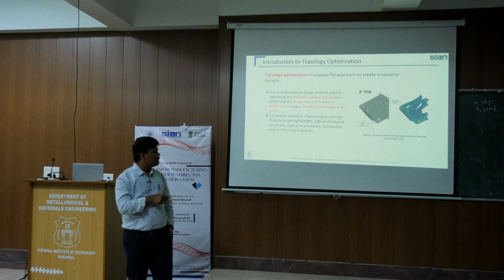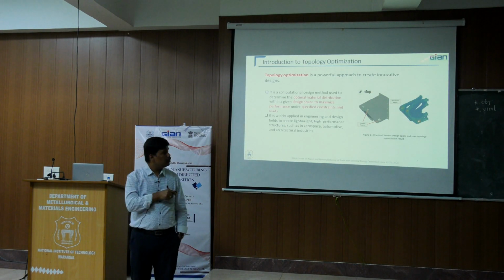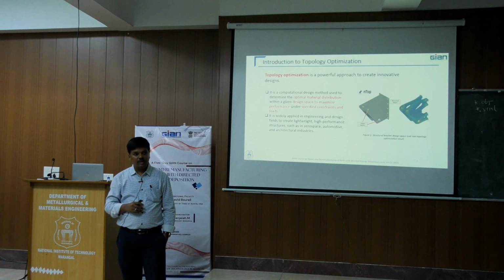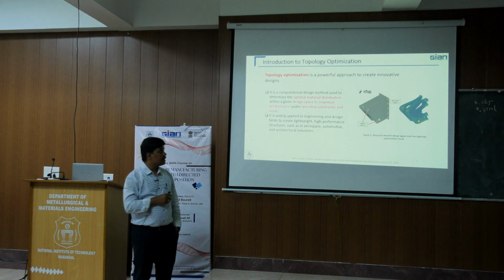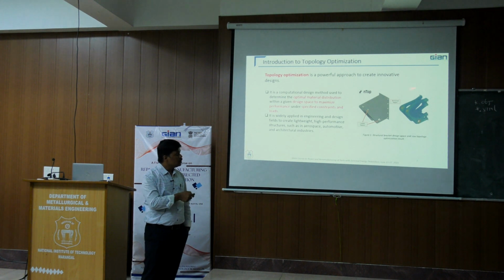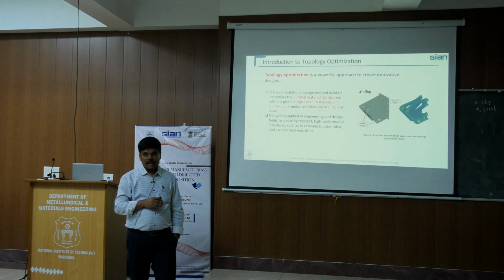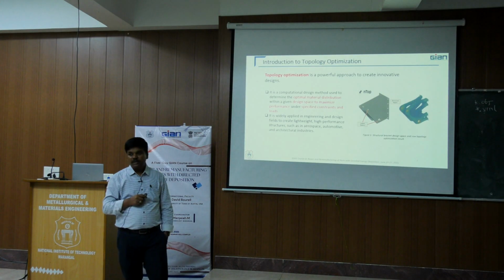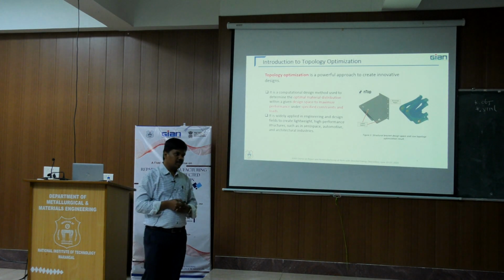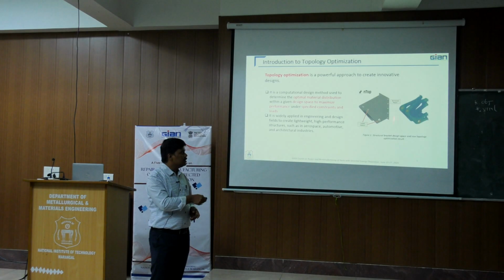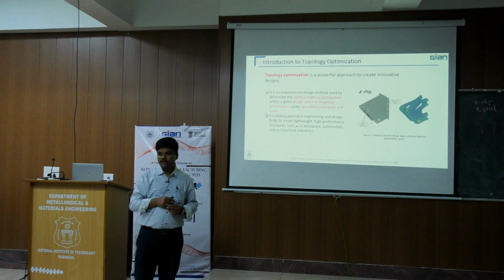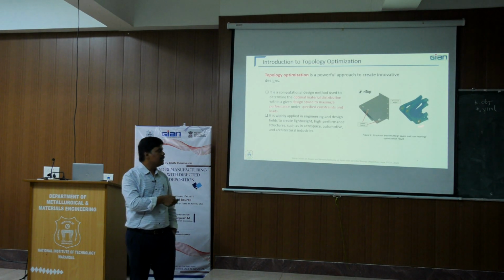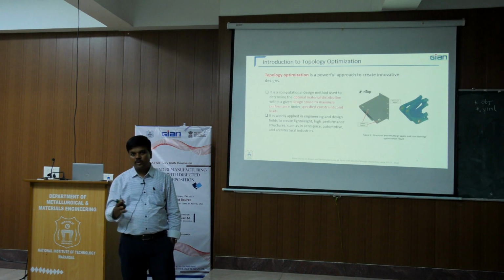That's what other people and one of our schools do. Topology optimization is usually done with software, and here is another example. They have tried to simulate where the load is acting on this model and where the structural part is existing, providing several constraints as well as material properties. And if you see, this is the raw topology optimization result. But raw will not be efficient to manufacture with respect to ready manufacturing.